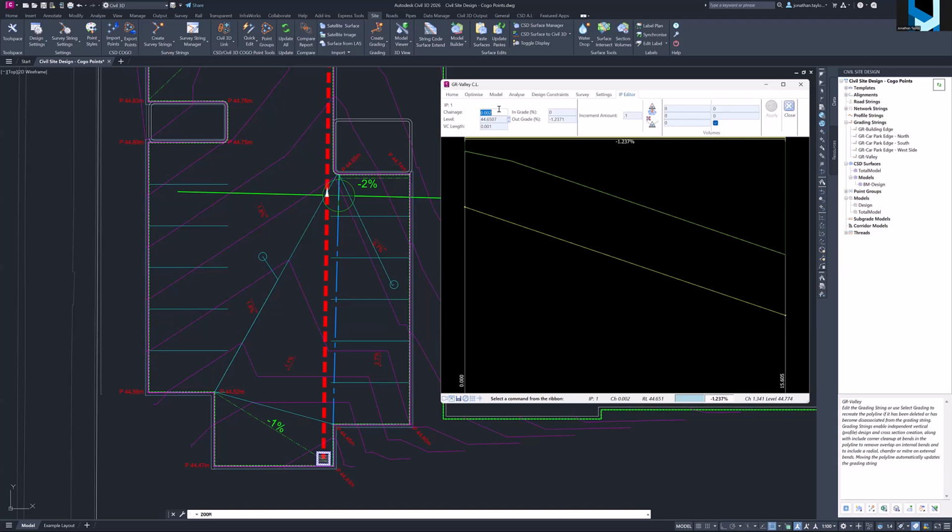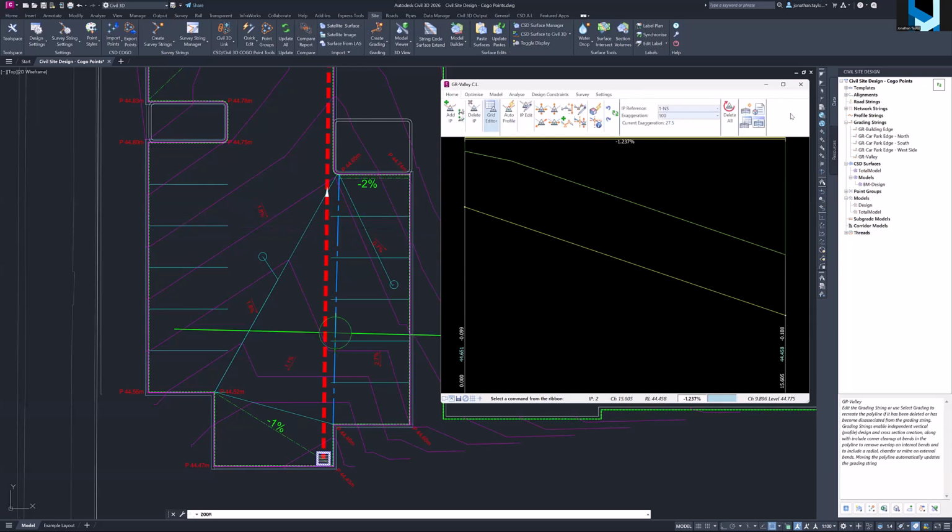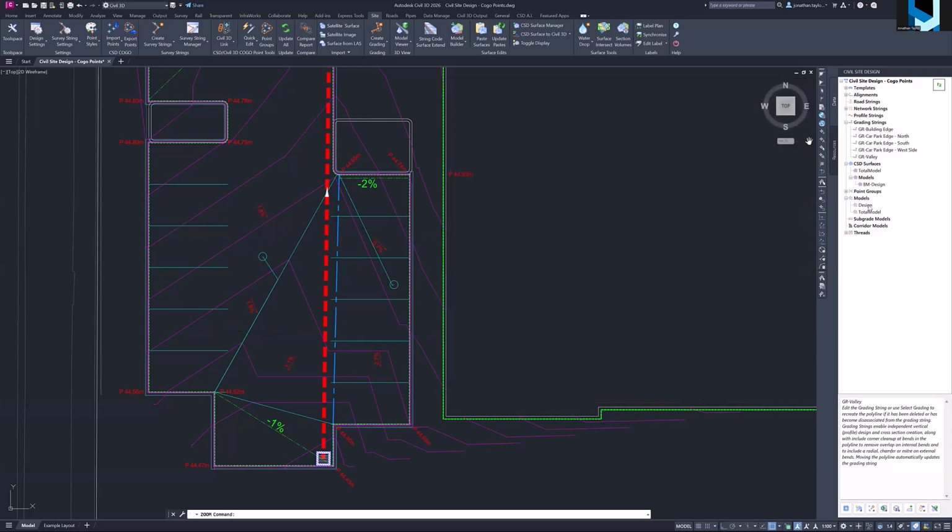So I would suggest if you come in here, you put 0 and press enter, and you'll know you've not got it because the text will be empty in here. Okay, click on close, click on the end IP. I can see what the chainage should be, 15.605. And obviously that reduced it by a very tiny amount, and then click on close. Close that down, and I'm going to right click on my model in Model Builder and go rebuild, which has then incorporated it into the design.